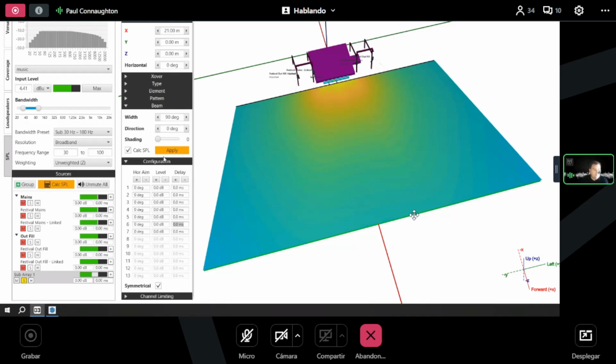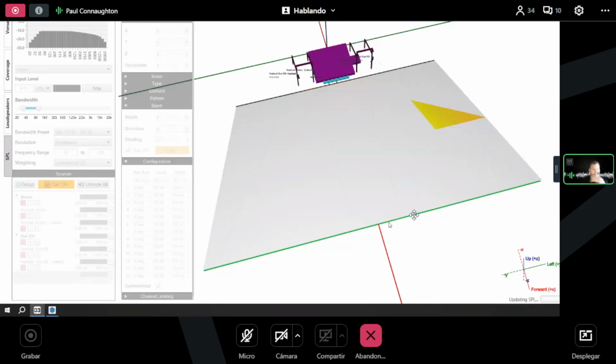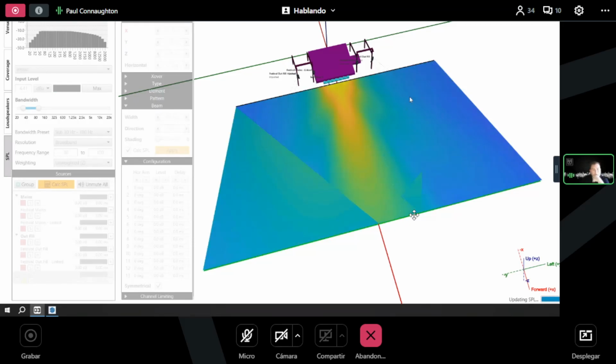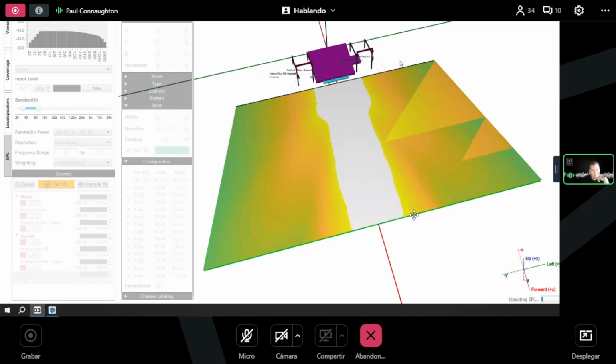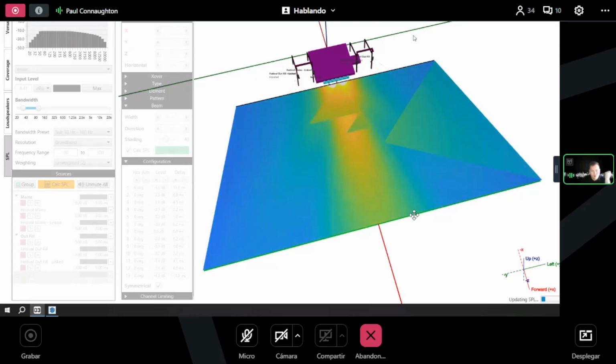If I now calculate that with that soloed, we go back to the sub array we had initially at first before we applied any of these changes in any of these parameter controls. I can now click my 90 degrees. We'll just do default 40% for now. Click apply. You'll now see that some level offset and some time offset has been added throughout the array into each source and required to achieve that coverage.